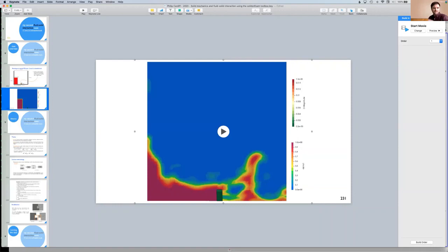So yes, it does. And with your deformed mesh, does that artificially affect the phase field? I assume you're referring to the volume of fluid field, like the alpha field. So does that affect it? Yes, when the fluid mesh moves, your underlying solver needs to be an ALE method, an arbitrary Lagrangian Eulerian.